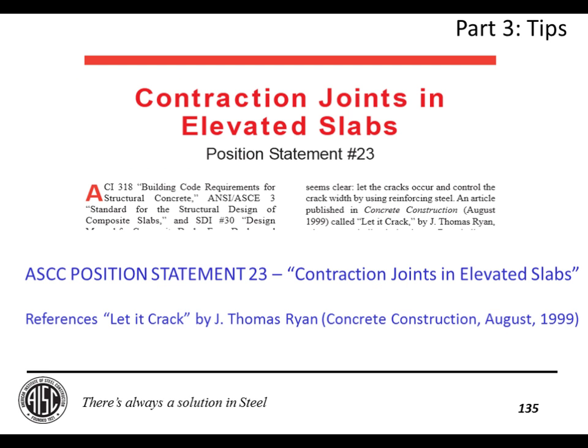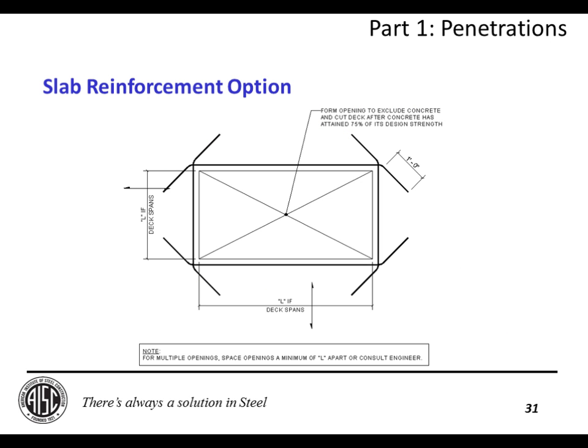Next question, I'm going to take us to slide 31. And this is, I guess, kind of a concrete question, but why would you not just extend the straight bars beyond the edge of the opening? A distance, because it's Ld. Yeah. It's really best to try to cross perpendicular to where the crack's going to open up.